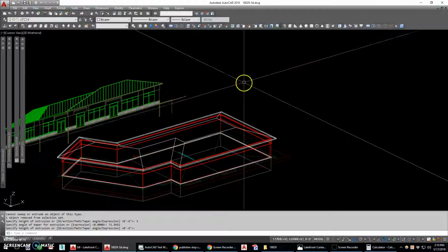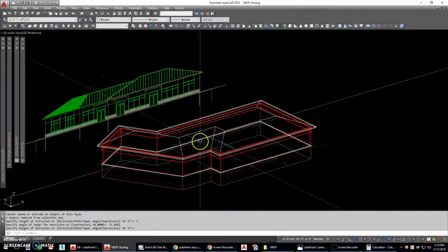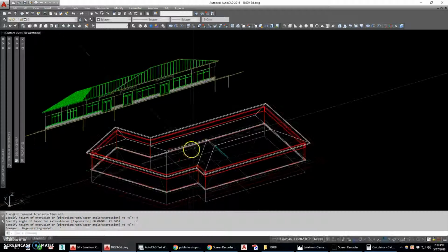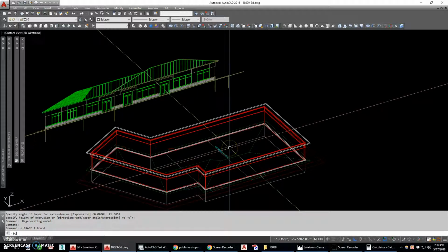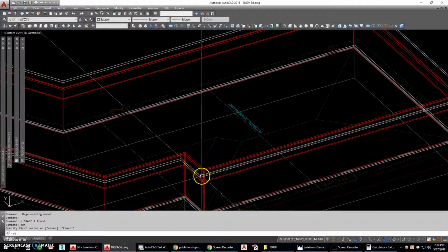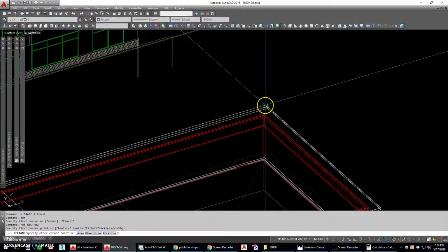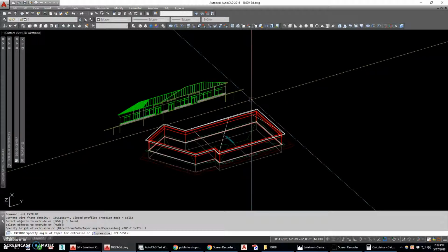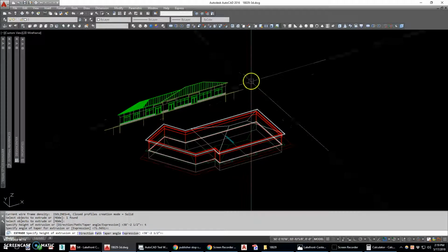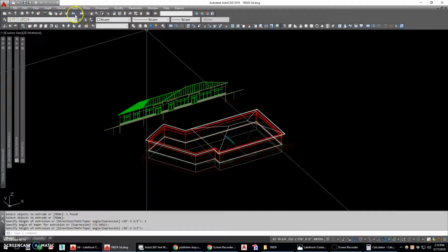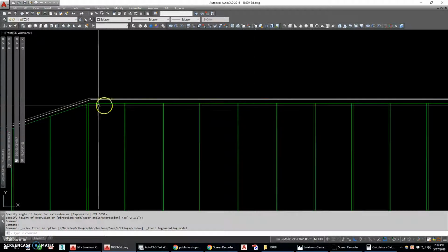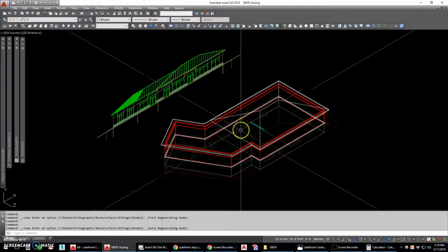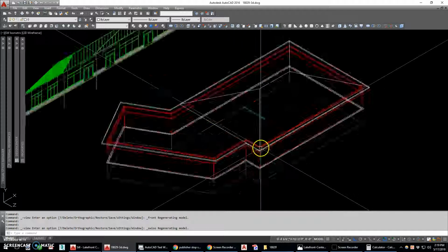And that did not work like I expected. But I think it gave me some of the things I need to make it work. Let's try it again. This time I'm going to draw a rectangle across here and extrude that up with a taper angle of that. Enter. Now if I look at the front view of that, it's not exact, but it's real close. And since everything we're doing is relative to this, that should work just fine.